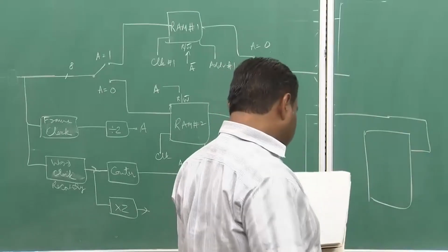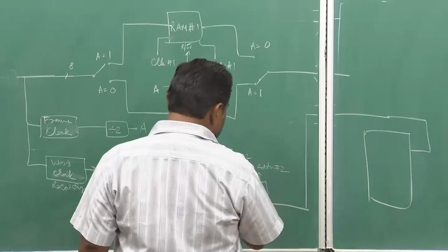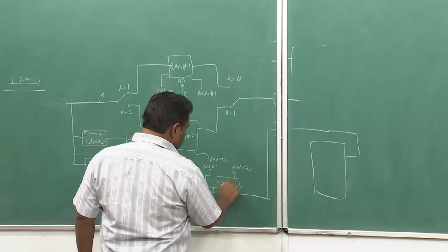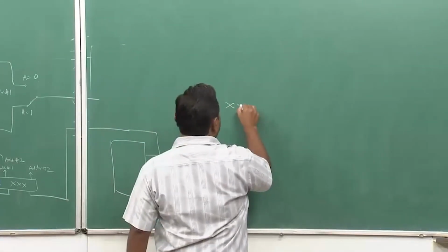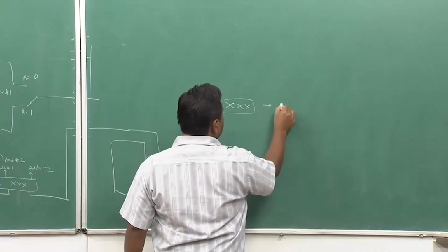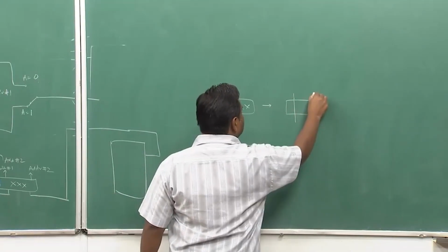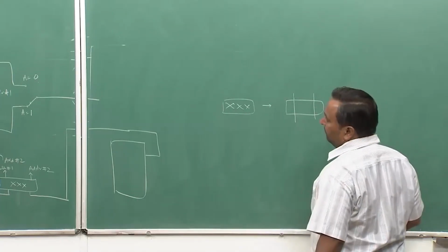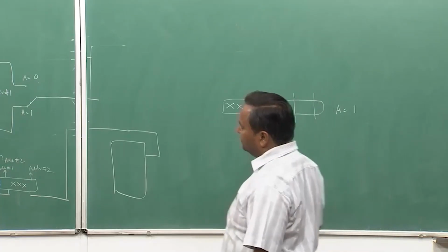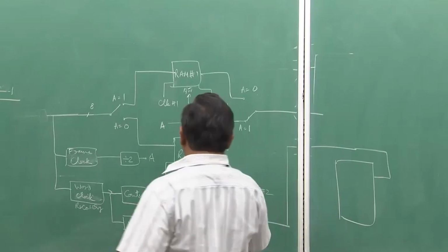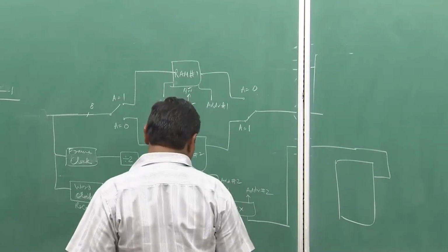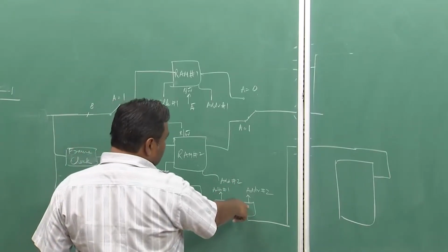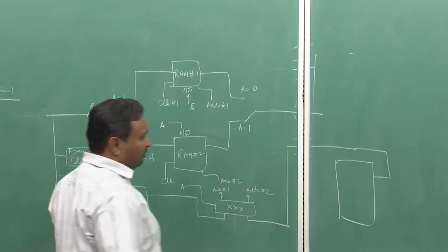Okay. So for this switch I call it the crossbar switch. So this will be the crossbar state when A is equal to 1, okay, because when A is 1 the counter value has to go here so that you can write down, while what has to be read out will be coming from address 2 which is going to come from the control memory.